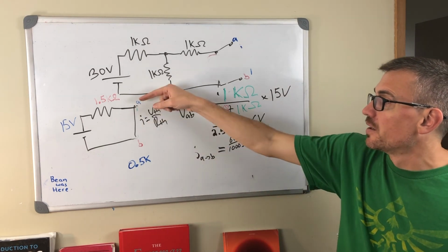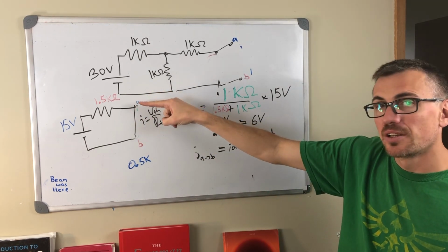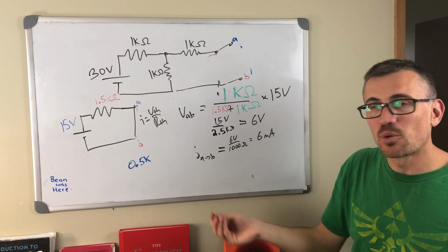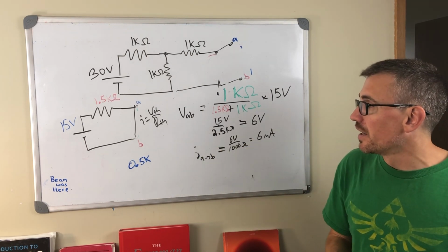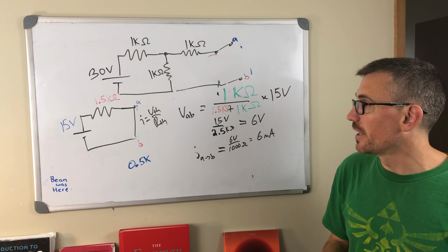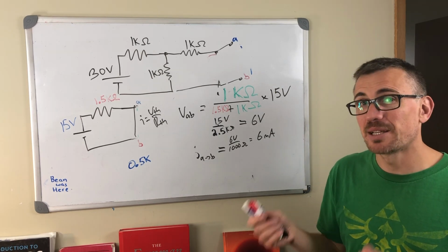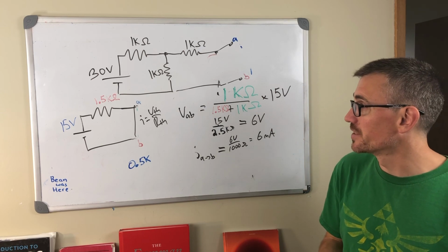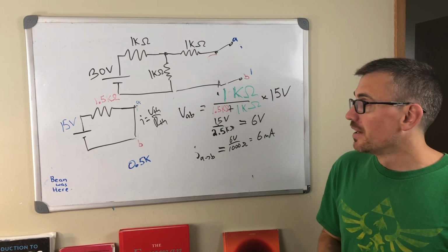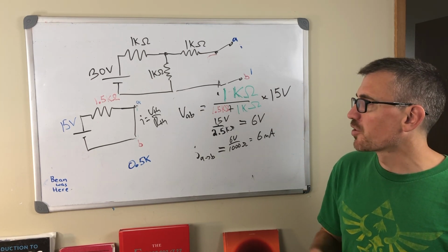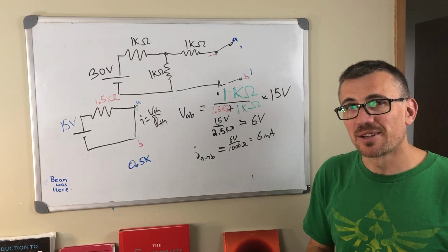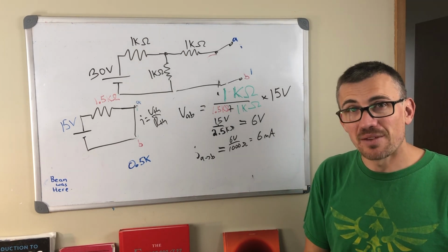So I can just play with this load resistor to basically get a system of equations, get enough equations as there are unknowns, and extract V Thevenin and R Thevenin. So practice makes perfect with these equations, with this technique of Thevenin, and after a while the intuition becomes a bit more clear. Okay, so that's it for Thevenin's theorem.